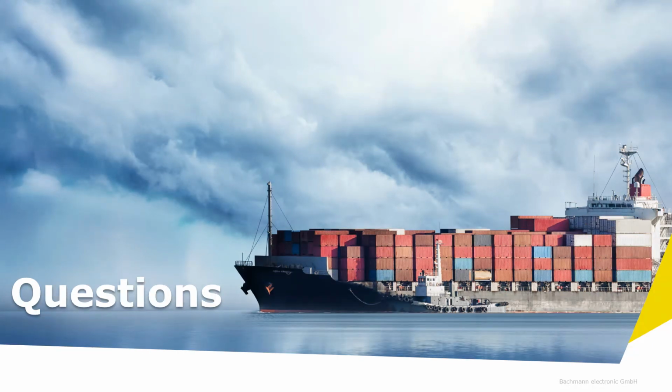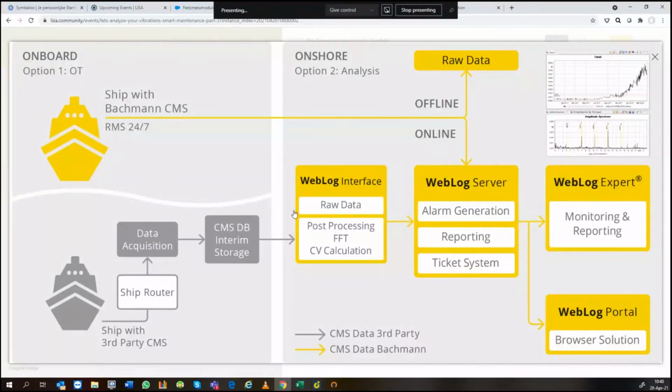The way that works is we write a data converter running on the time signal from the other company's data, and then post-process that through and put it into the Weblog server, which holds all our data. Unfortunately, the vibration community has never really got together on having a single format for data. So virtually every system you buy has a slightly different data format behind it. But the good news is most of the formats are quite simple to decode, so you can just read them into whatever your own system happens to work with.